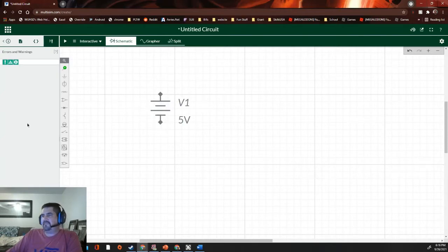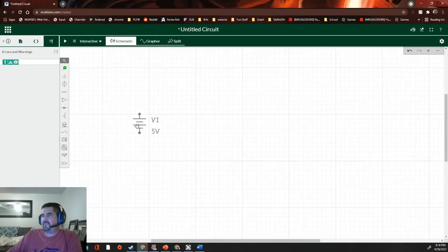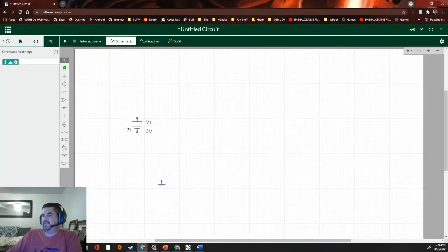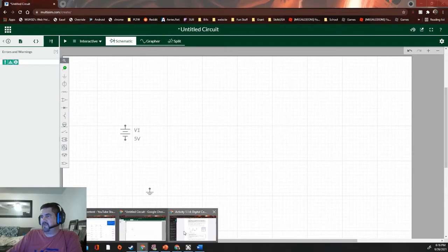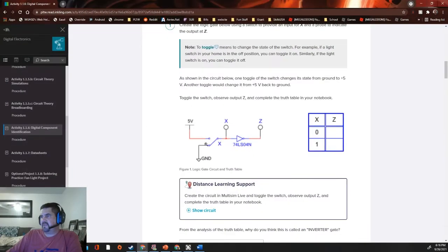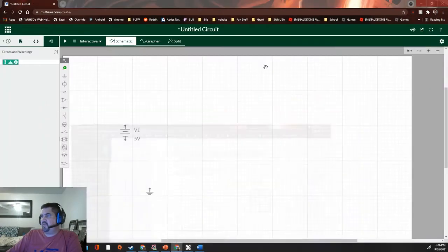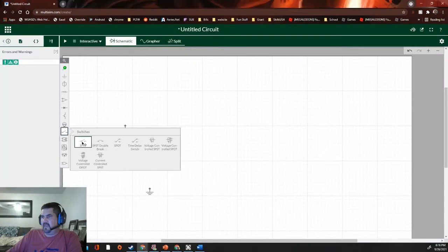So it has that. So we kind of have a positive and negative at the same time, but we're also going to need to click this and get that ground for the negative. Just the way it is. It's the way this works. We're going to need the next thing, which is over here. We're going to need this thing, which is a switch. It's a single pole double throw, SPDT. So click here, and that's a single pole single throw, not that one. We need the single pole double throw, this one, SPDT.